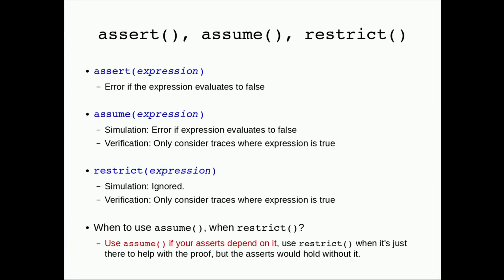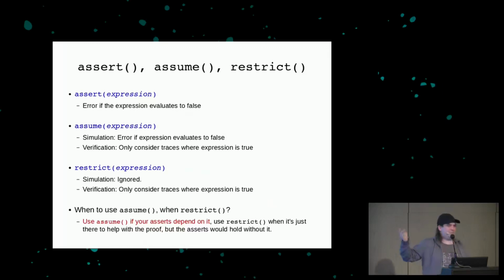That's great. So for formal verification, you need to have some additional statements in the Verilog language. Namely, you need to have a way to create assertions, and you need a way to create assumptions. And we've seen those assert and assume statements already in the Hello World example I just showed you before. So when you have assert some expression, it just says, we say this expression must always be true. And if there is a way to make this expression false, then this is a bug, and the tool should tell us how to get into this state, should demonstrate the reachability of this bug to us.